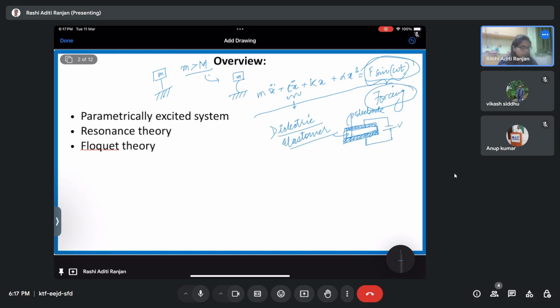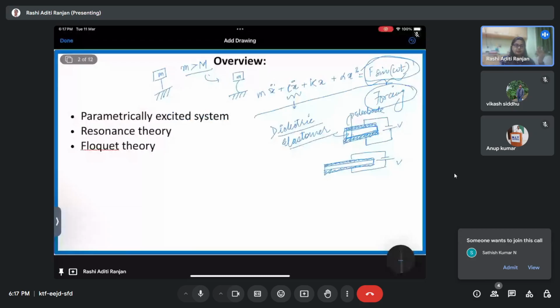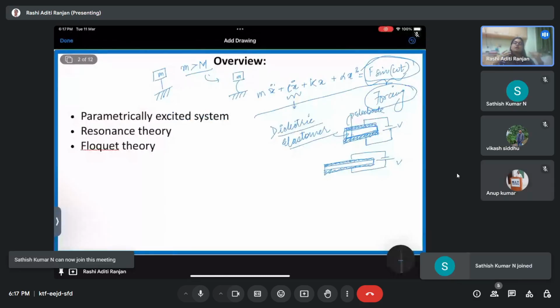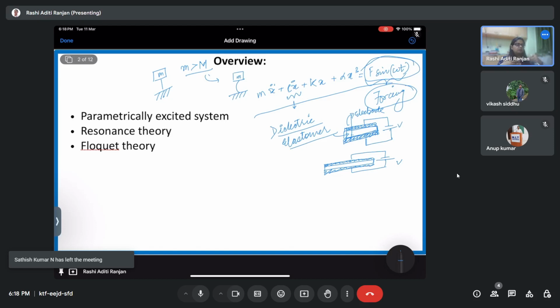The thickness is going to reduce after the voltage is applied. Now, if I consider that the material is incompressible, then the reduction in the thickness will lead to an increase in both the lateral directions. So when we write the equation of motion, there are various things we consider, like the stiffness of the dielectric elastomer, then the damping, and everything.